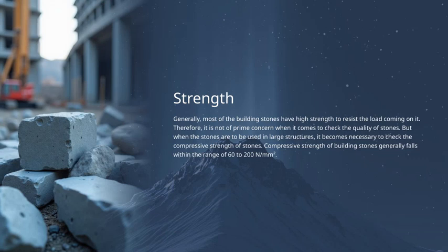Let's talk about strength. Generally, most building stones have high strength, which helps them resist the loads placed on them. Because of this, strength isn't usually the primary concern when we're just checking the quality of stones for typical use. However, when stones are intended for large structures, it's important to actually check their compressive strength. This is because larger structures demand more reliability, and knowing the compressive strength ensures the stones can handle the load.